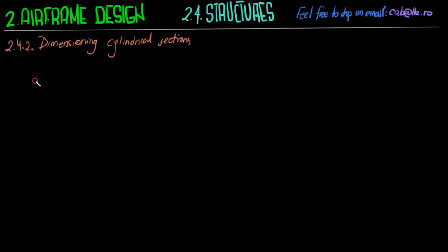It mixes up the sigma for the ultimate strength of a material and sigma as a load, so it can lead to a lot of confusion. Because it's a non-guided sounding rocket, I'm not going to take into account any maneuver bending moments. So where Fleeman talks about maneuver bending moment, I'm not going to add them.